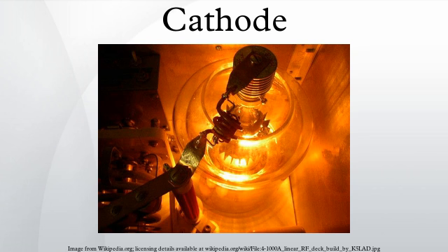This is due to the resulting internal field and corresponding potential barrier which inhibit current flow in reverse applied bias, which increases the internal depletion layer field. Conversely, they allow it in forward applied bias where the applied bias reduces the built-in potential barrier. Electrons which diffuse from the cathode into the p-doped layer, or anode, become what is termed minority carriers, and tend to recombine there with the majority carriers, which are holes, on a timescale characteristic of the material, which is the p-type minority carrier lifetime. Similarly, holes diffusing into the n-doped layer become minority carriers and tend to recombine with electrons.